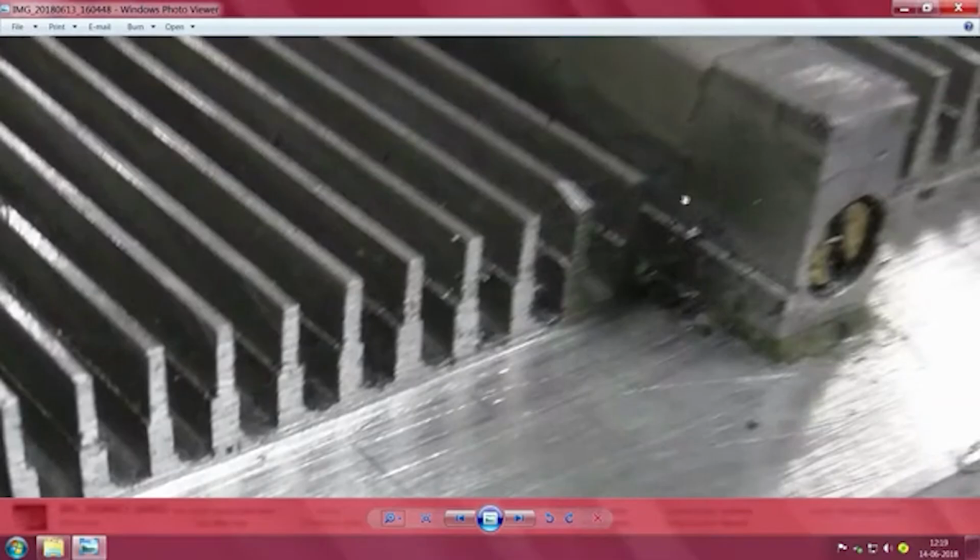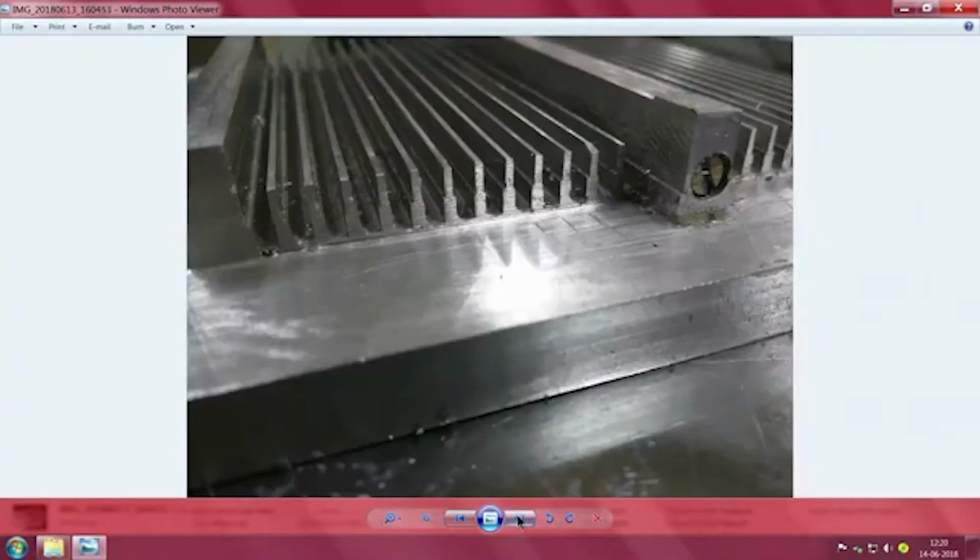This intentionally has been made as a separate piece, saying those channels, do they really behave the way we want with an S-shaped thing going on like this, or if we remove it, maybe we have one input header and one output header, and the flow will be better and we can get about the same heat transfer coefficient. So, this has been attached here. If you do not want it, eventually for ease of fabrication, maybe you can just remove all these things and make things a little easier for us.